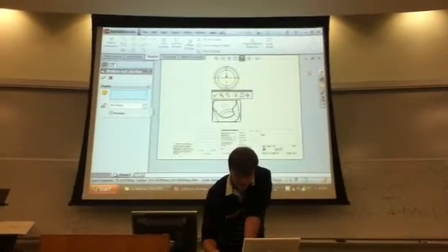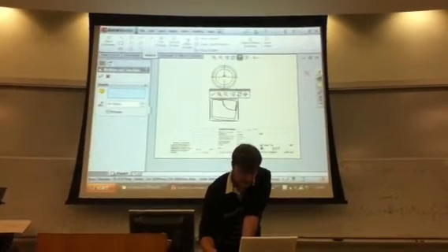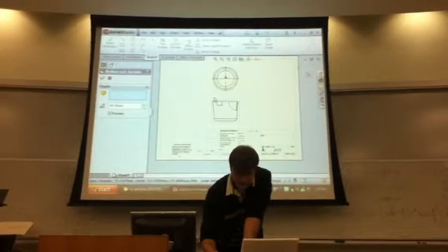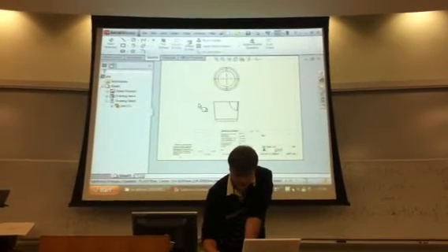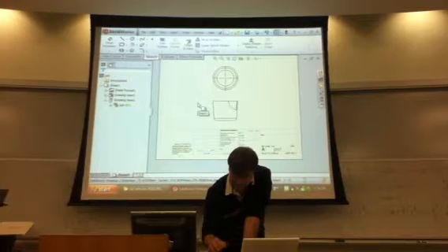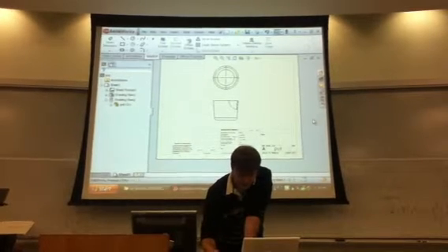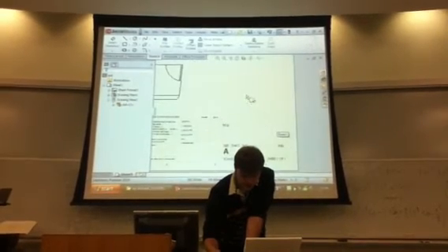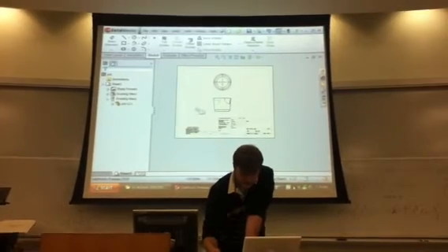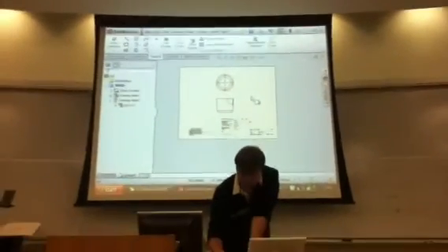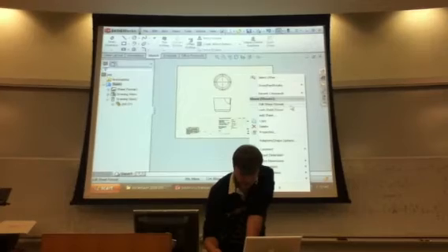So there's our halfway line, and the circles, well, you get it. Okay, good. So now we have a broken out section view. To edit the words on this sheet, we can right-click anywhere that doesn't have anything on it, on the sheet, and press Edit Sheet Format.